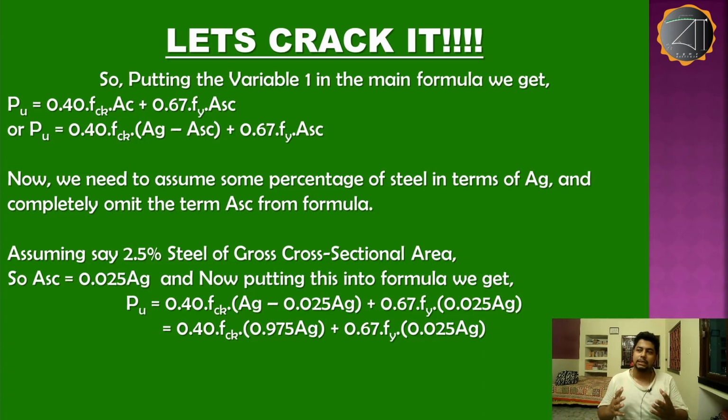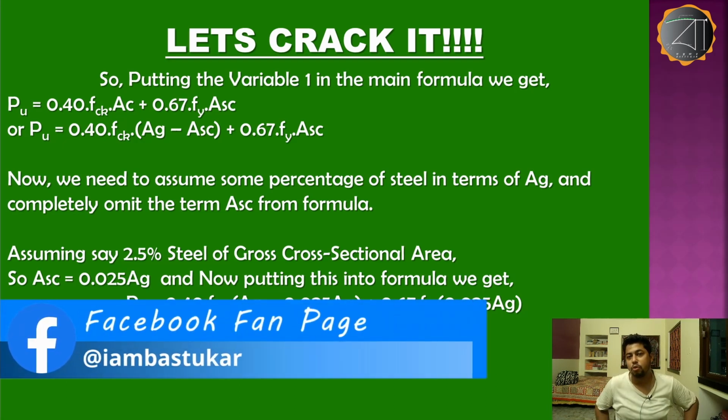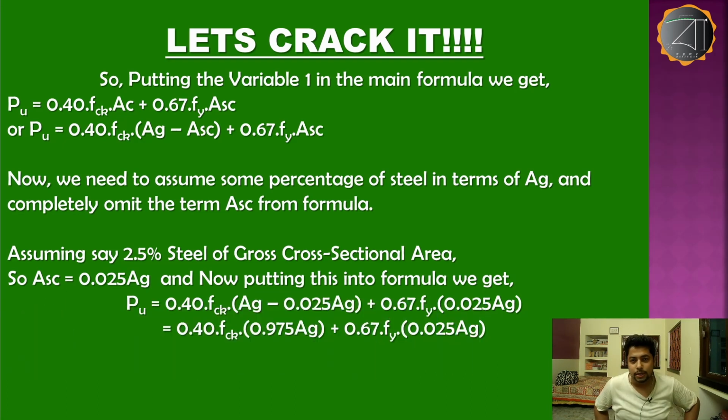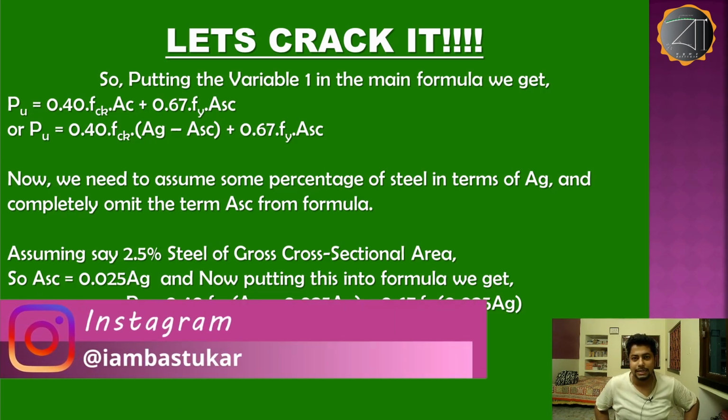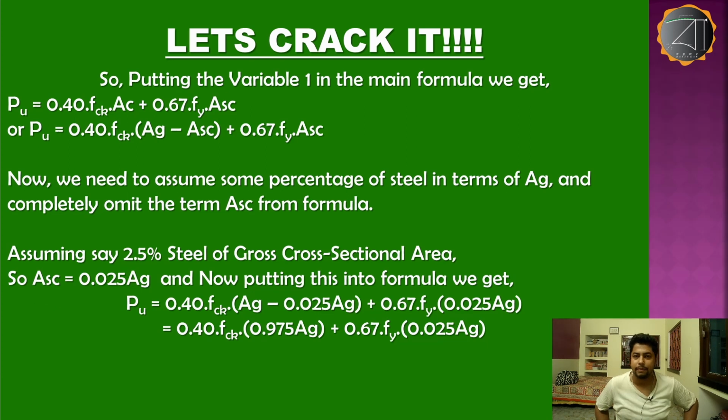If we increase the area of the steel, then we will have a slender column because the area of concrete will be lesser, because steel will take much more load, as the load taking capability in direct compression for steel is much higher as compared to concrete.